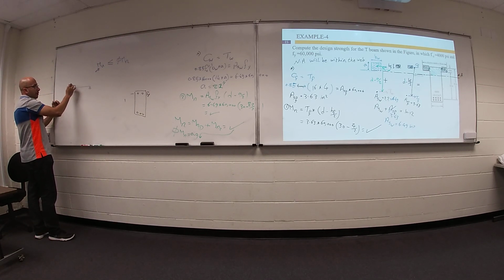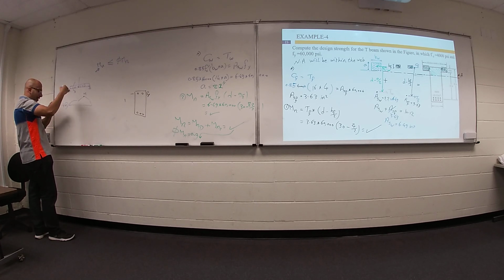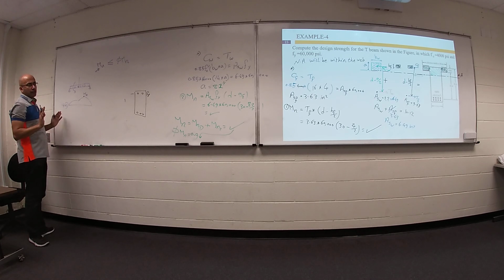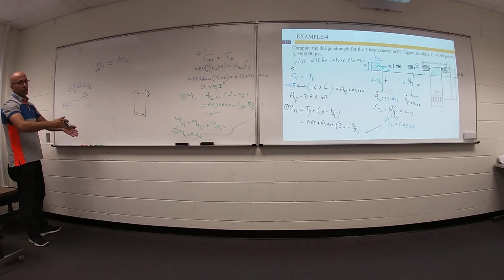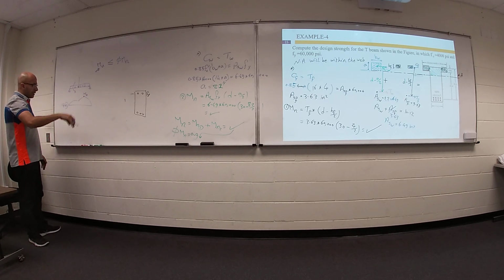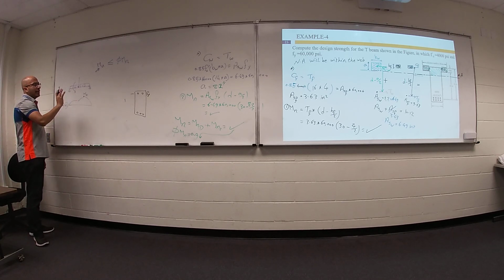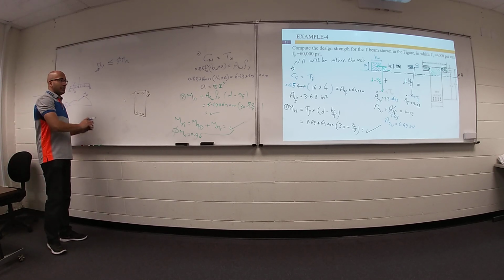You have a beam, maybe with uniform distributed load, concentrated moment, whatever. And you draw your bending moment diagram. What is the final maximum moment, which is called M u, based on 1.2 dead load, 1.4, 1.6 live load, and you get your final maximum moment. This moment from